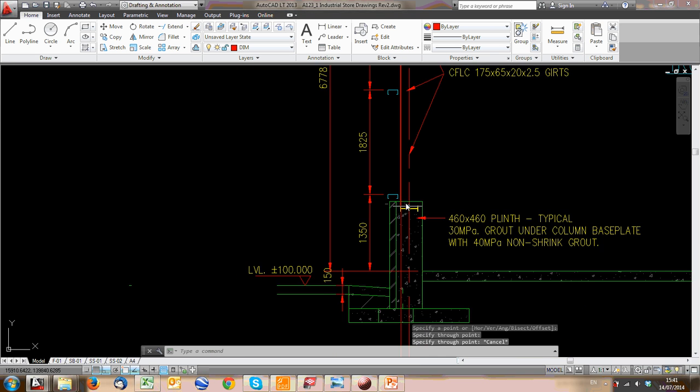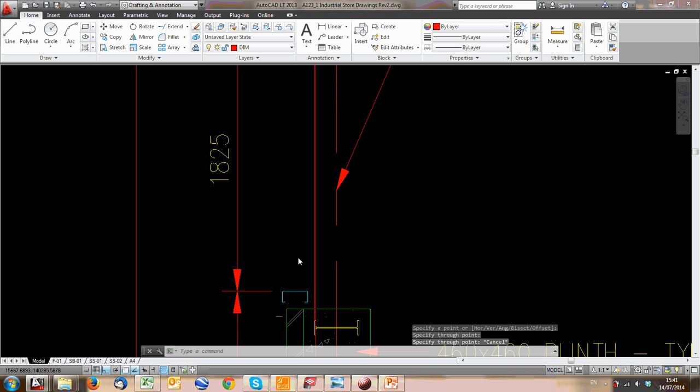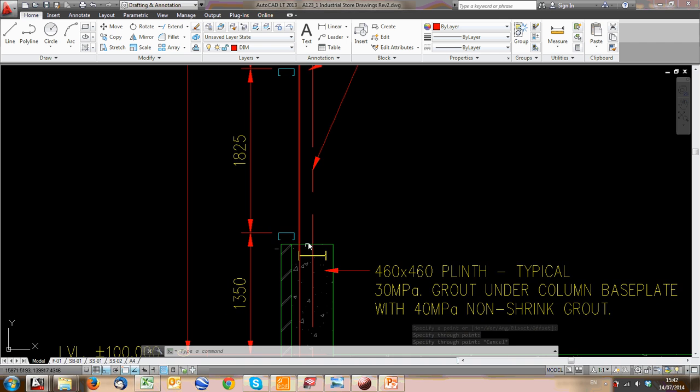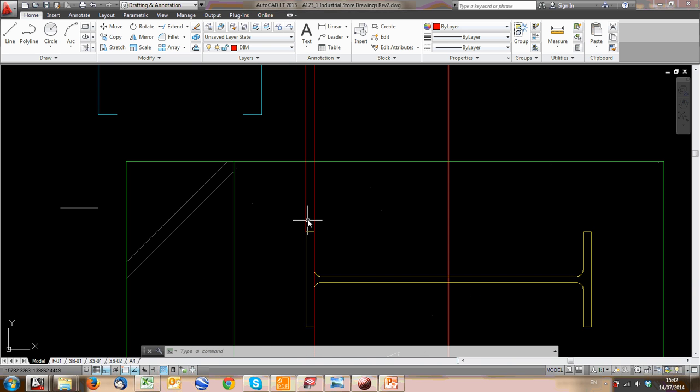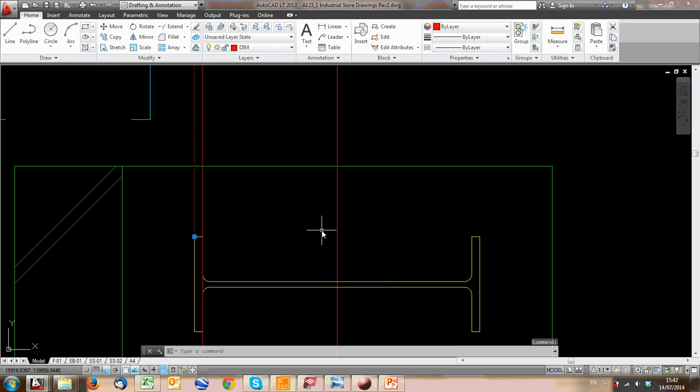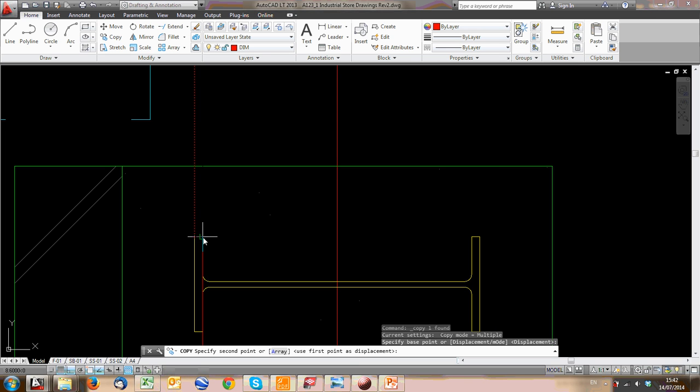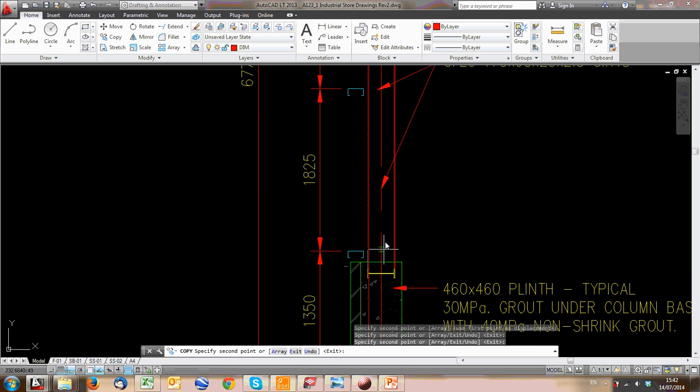I've got a line that now goes up, so either I can draw it using just a standard line, a construction line, or I can draw the first line. Now I can copy him across, so I can click copy. Now I need to specify a base point at the bottom, copy, specify base point or displacement mode. So I'm going to select an end point there and move him across and click and click. So I've created a couple more lines.